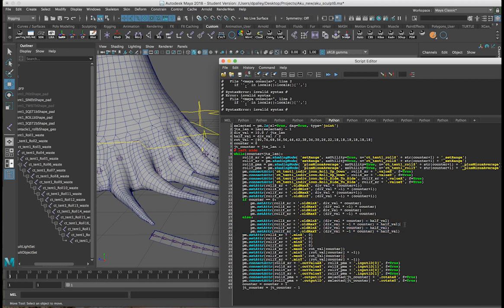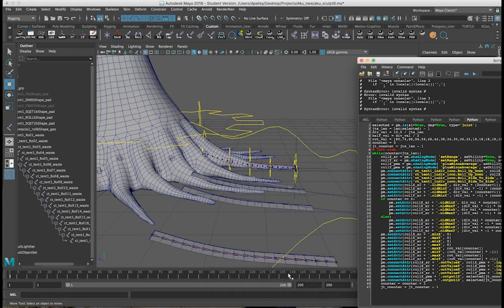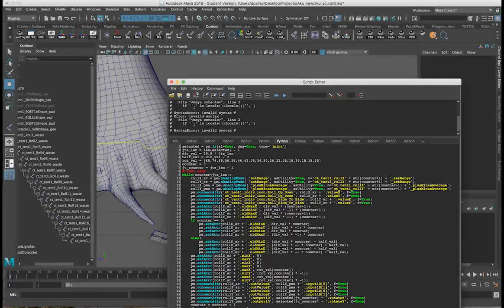what we use here is, essentially, when I initially did this without the half value, when it started to rotate, it would rotate fully, and then it would kind of pop, and then the next joint would start rotating, and then it would pop, and it would keep popping once the max rotation was reached for each joint. So what I wanted to do is create a smooth transition from one joint to the next. That's what this half value is for: I start the rotation halfway into the previous joint's rotation.